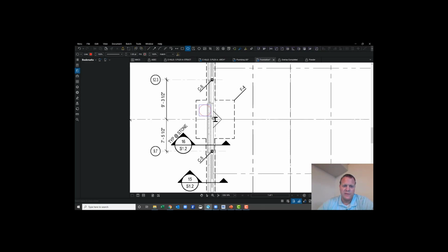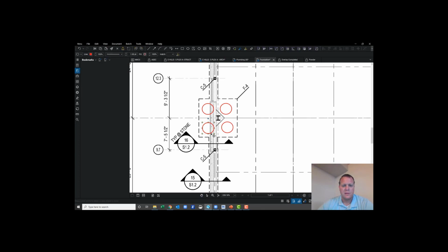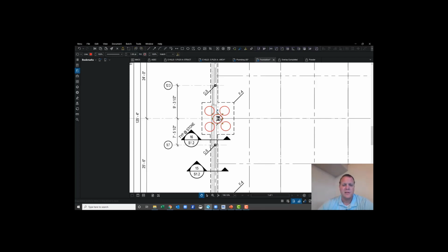And I believe there were 5 of them per, I think, per footing. Could be wrong. But there were geopiers underneath the footing. So if we had a roof drain pipe coming right down through here and then going below the footing to the civil, it's not only going through a concrete footing, which is probably not too good for the structural engineer to think about, and this is an H column, so most likely this is not just a gravity column.